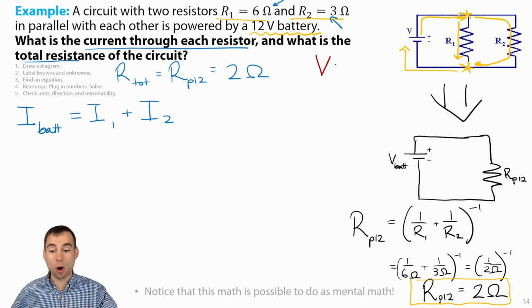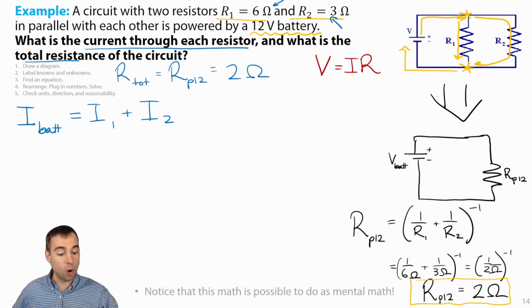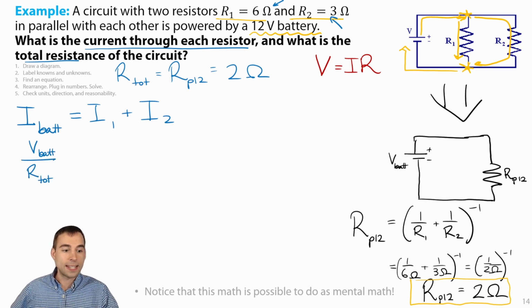Once again, thinking about Ohm's law, we can substitute for an unknown variable with other known values. The current being output by our battery will end up being the voltage of our battery divided by the total resistance of the circuit, as if we were just looking at our simplified equivalent circuit right here. The voltage supplied by the battery must be taken care of by this entire resistor.